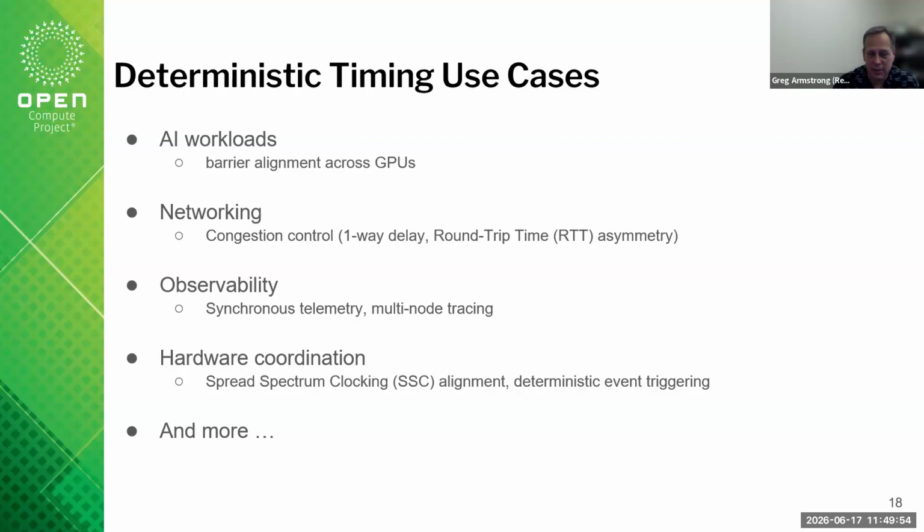I may have a server that has multiple cards plugged in, and I don't want to worry about how to keep them all nicely aligned. I can now use EPPS to say, here's a marker, keep it aligned. It doesn't necessarily mean you have to create the bus's clock off that 10 megahertz, but that marker is going to be very stable and its relationship to the other cards is going to be known. So that marker could be used for whatever purposes it's needed.